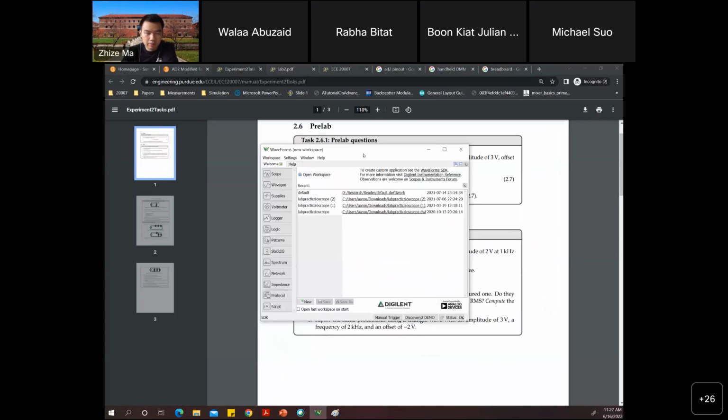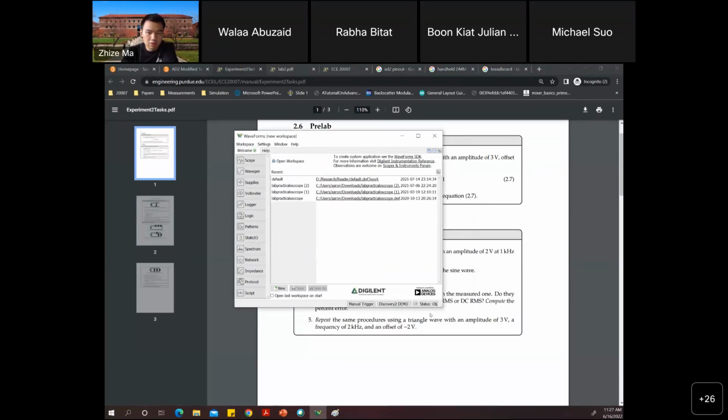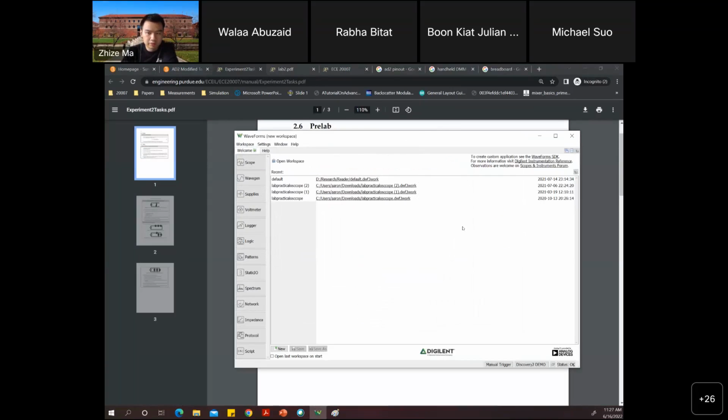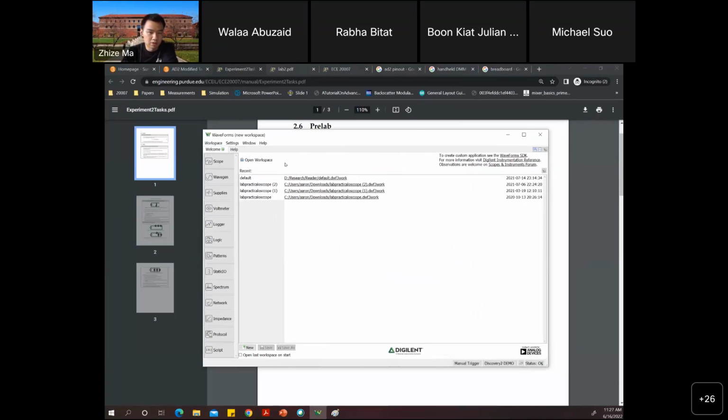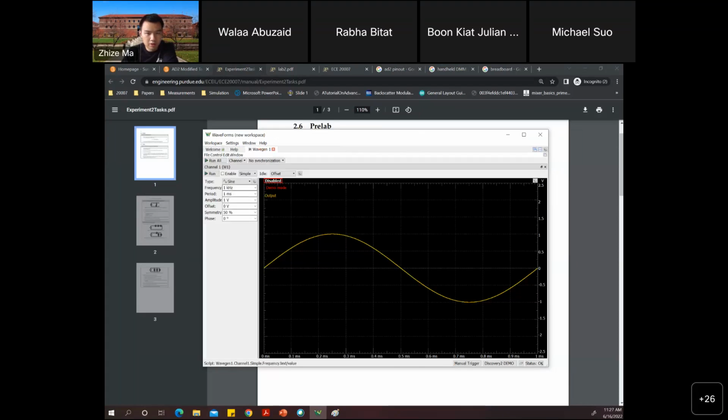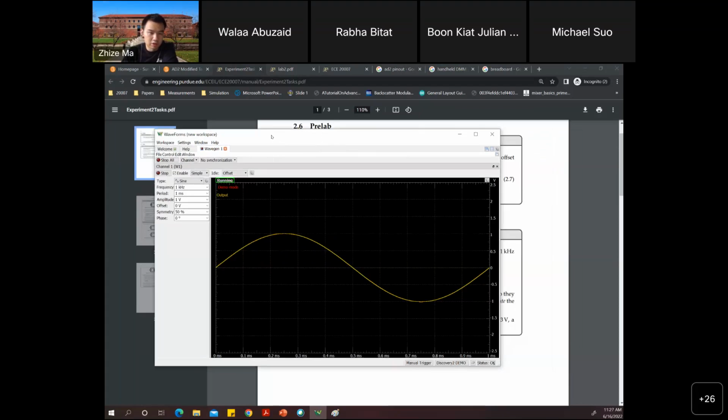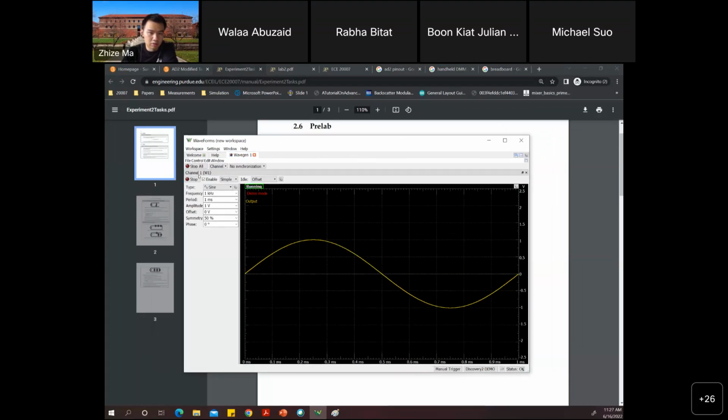So as we mentioned, you're going to use AD2 to generate the sine AC signal. So there is a wave chain here. That's your wave generator. If you open this, basically there are two channels. Right now I just show one of them. That's channel one, which is W1. If you check the pin out, there's a W1. That's where the signal comes from.